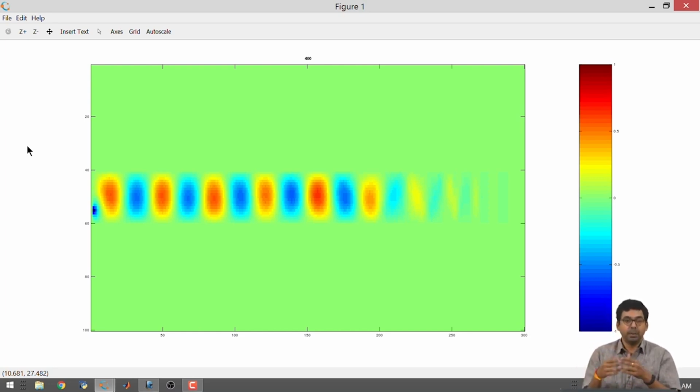It is telling that first of all, when the spacing between the waveguides was very large, okay, and your source is of some frequency, maybe the number of modes that can be supported by the waveguide is higher, okay. And if the number of modes supported by the waveguide is higher and if your operating frequency is above the cutoff for more than one mode, then you may be able to excite more than one mode, all right. That is why you are getting some very different patterns when you move the source from top to bottom of the waveguide, make it asymmetric, etc. But if your plates are going to be closer to each other, the number of modes that you can excite for a given operating frequency is lesser, maybe it is just one in this case, right.